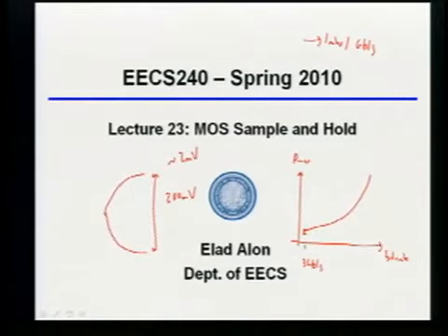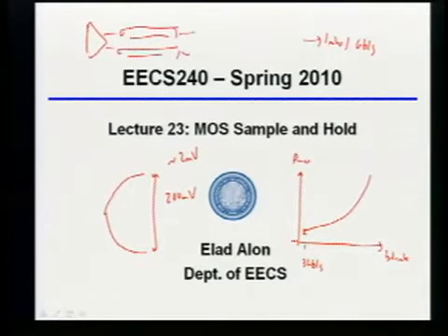Don't make me start picking on you guys. If our swing only needs to be 200 millivolts, then can we get away without the comparator? Not quite. This needs to be a digital level, though, right? In other words, I need to actually reject noise. Maybe you're saying, okay, I could just build my transmitter and blast this thing so hard that I have a volt of swing over here and still get maybe 100 millivolts of swing over there. But I want actually full digital levels.